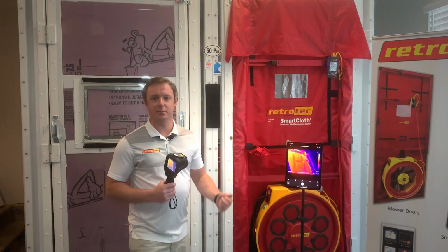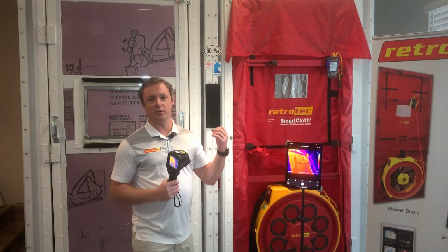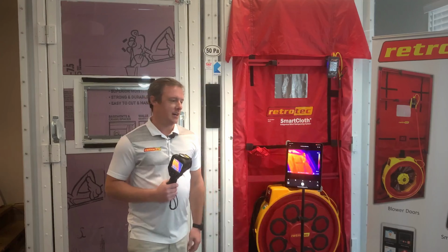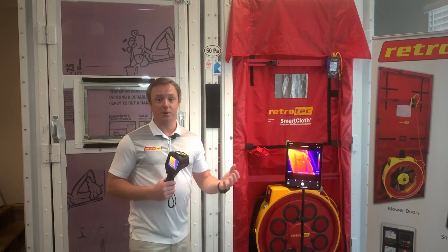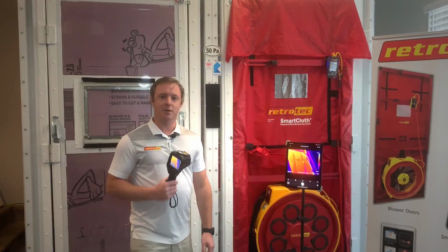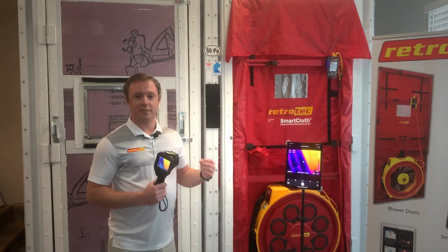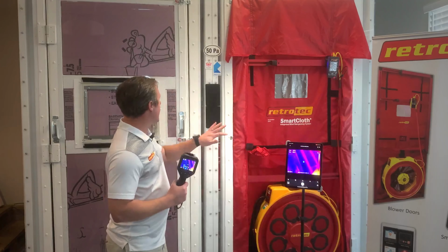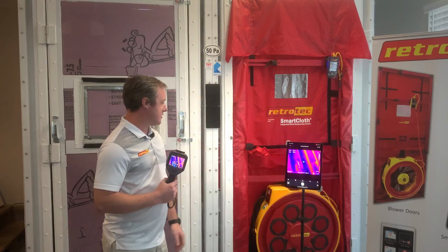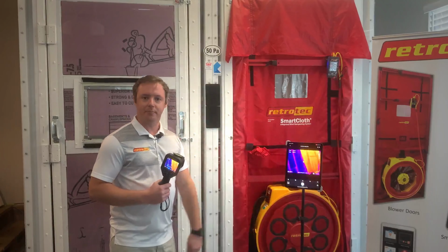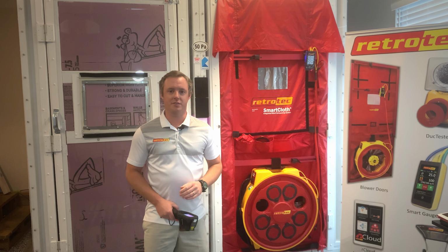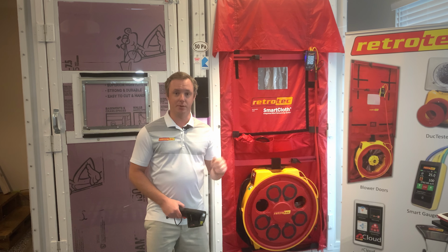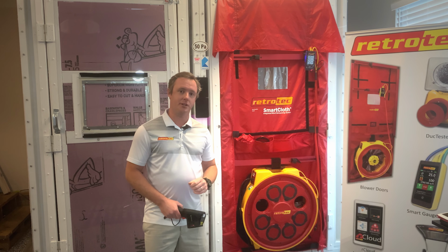Sometimes it just depends on the building that you're testing, and it depends on where that leakage is occurring and where you want to capture that image. Sometimes it's nice just to do both and see what you come up with. So I'll do an example of both of those today, but now we'll start out on the outside of this structure, and then we'll work our way in. What we'll do first is a quick scan around the building without the blower door running, and then we'll turn it up to 5 pascals of pressure.